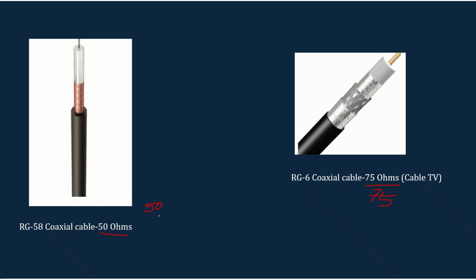Normalization means just dividing by the characteristic impedance. If we normalize the impedance, we can use the same Smith chart for any transmission line problem. Whatever the characteristic impedance, we can just normalize the impedances and use the same Smith chart.